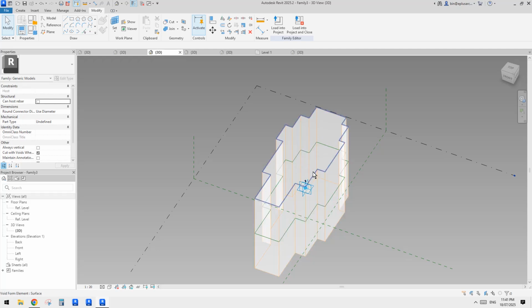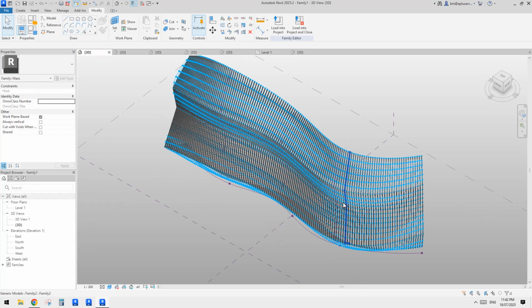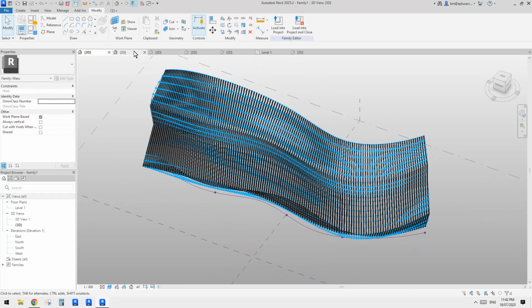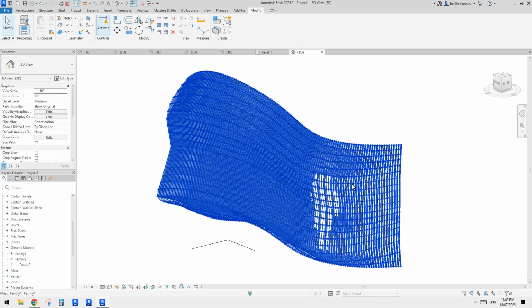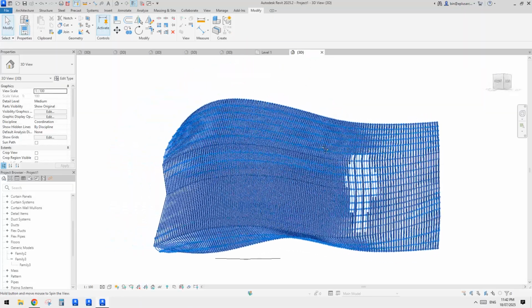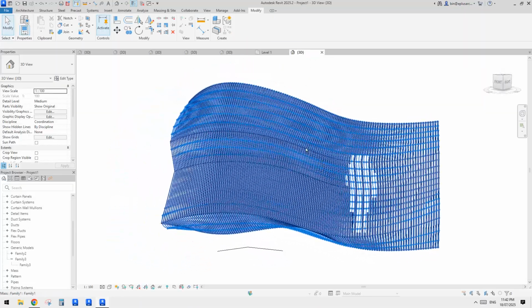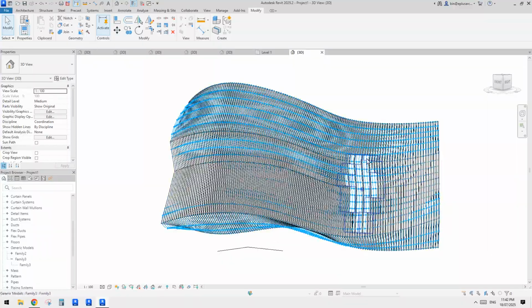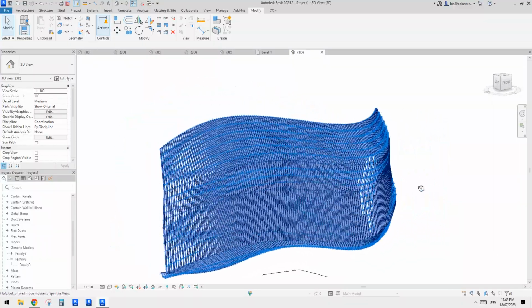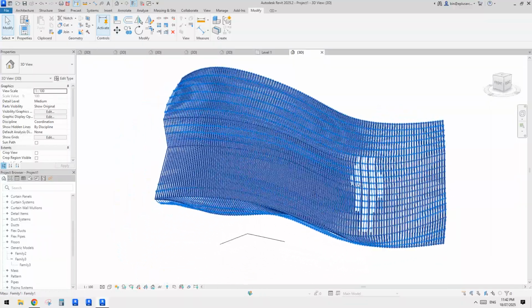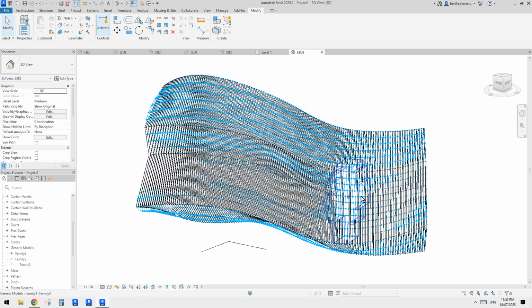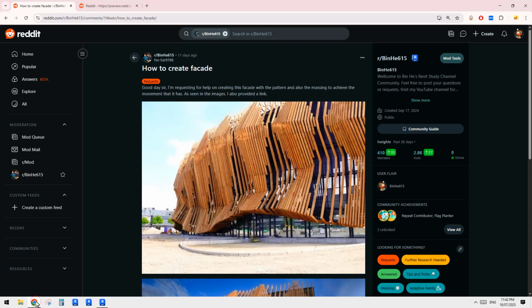Okay, so a mass void with this box ticked, and then we placed it into this project, and then we use cut geometry to cut these, right? So this is one of the options. So it's quite manual, but I think it's not too hard, right?